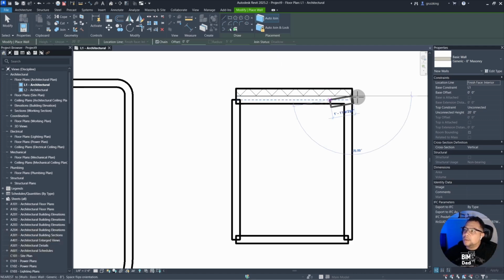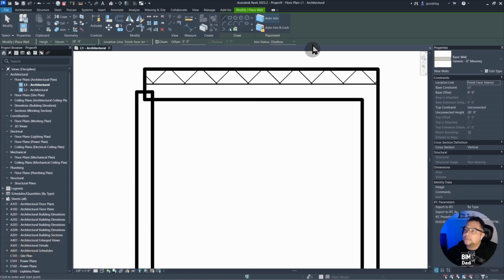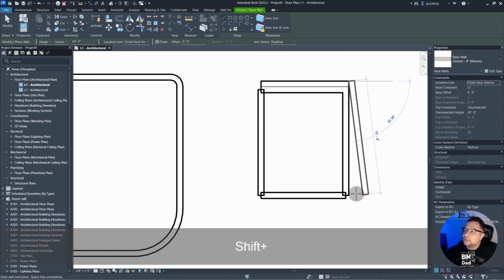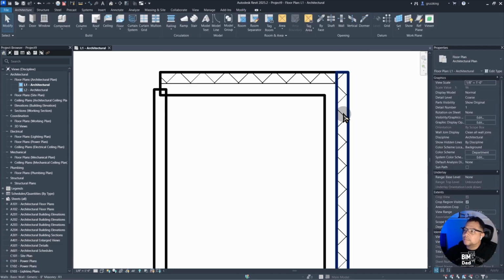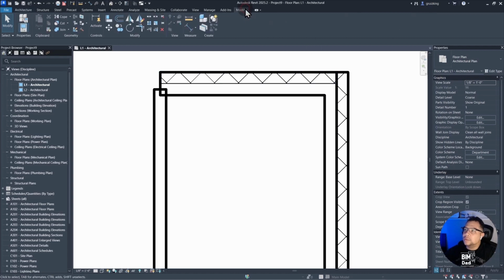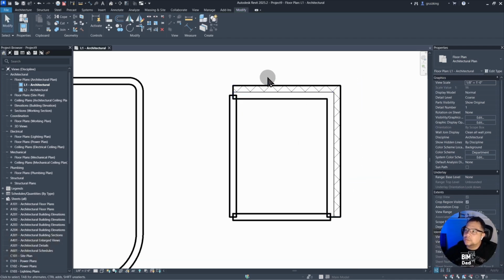I'm placing a masonry wall. You can see how now I have a nice thin common line here. I'm going to get rid of the auto join and then draw another wall along this side. And you can see now I don't have a nice thin line there. That's what the auto join does. It basically eliminates the need for me to go to Modify, Join, and then manually join these two walls. I'd also have to do it at the corners, so it saves quite a bit of time if you're dealing with existing renovations.